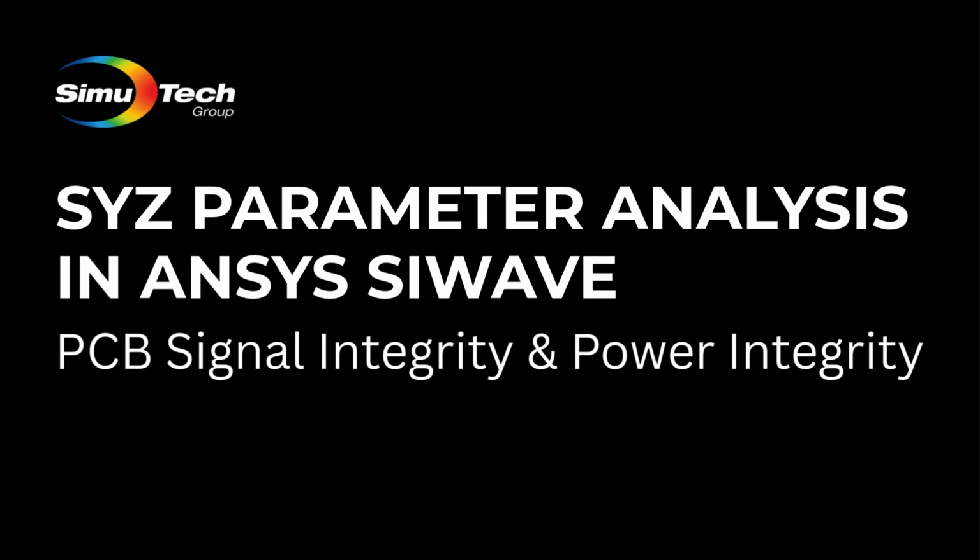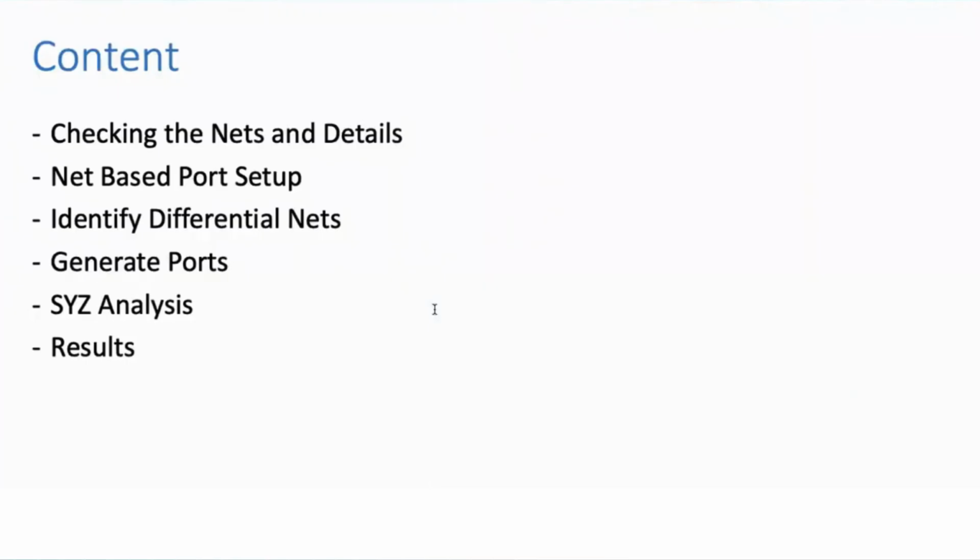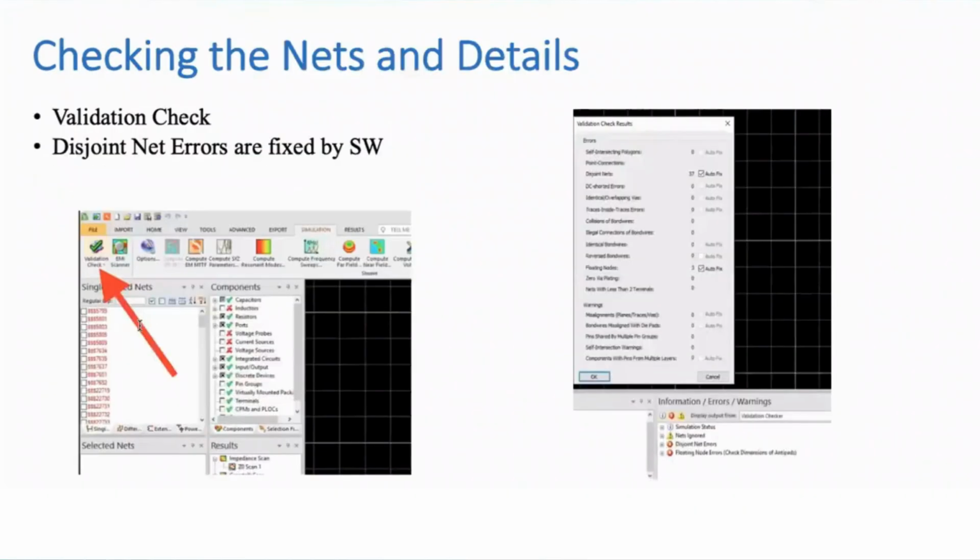So I'll start with the content. That's checking the nets and details. Then we talk about net base, how we set up the port. Then identifying differential nets. We generate the ports and the analysis and the result.